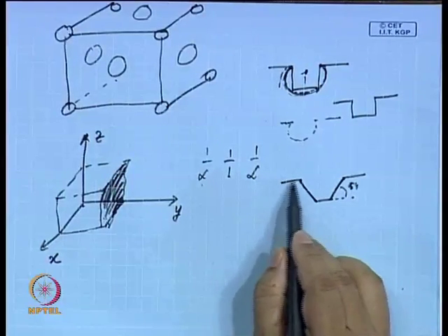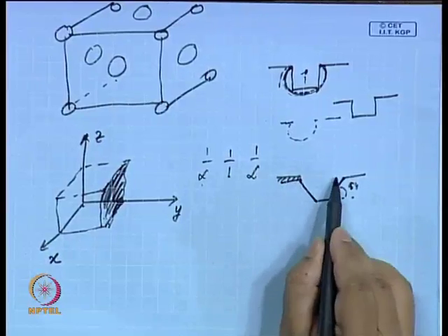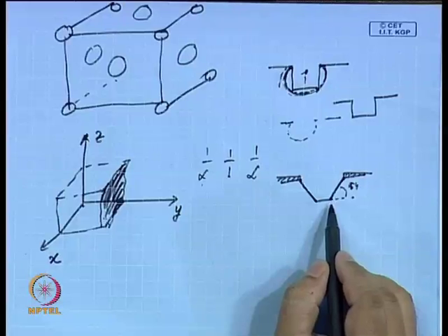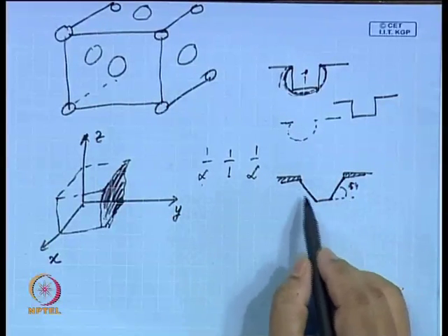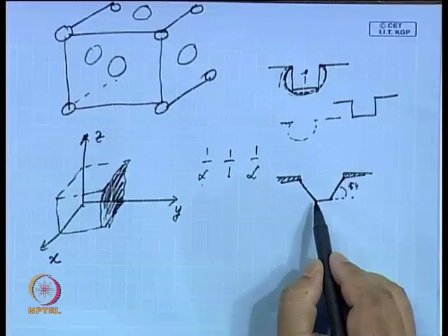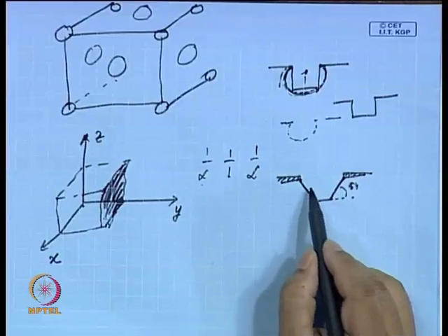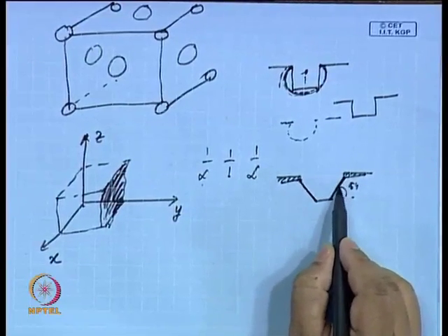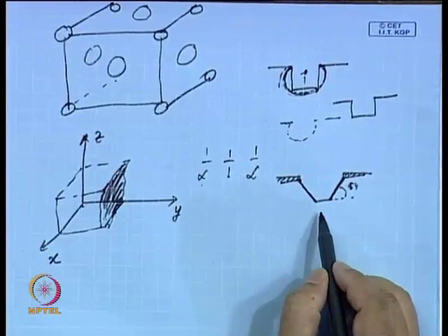So, the groove that is being formed. This part is protected by mask, this part is protected by mask, and you are trying to create a channel on a silicon substrate, and when you try to do that, what I say here is this form of etching makes possible cavities with facets. So, you have an inclined face here, it is not a straight channel. So, this is what you are going to form when you go for a wet etching.